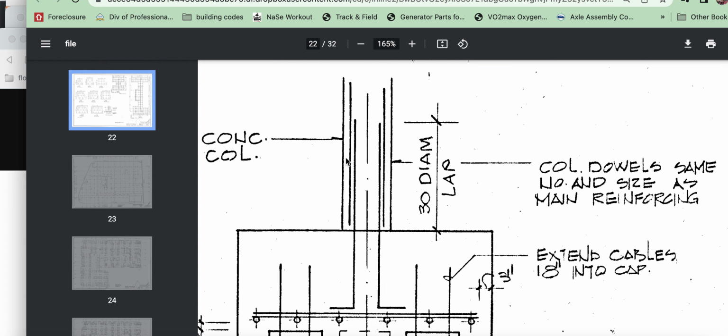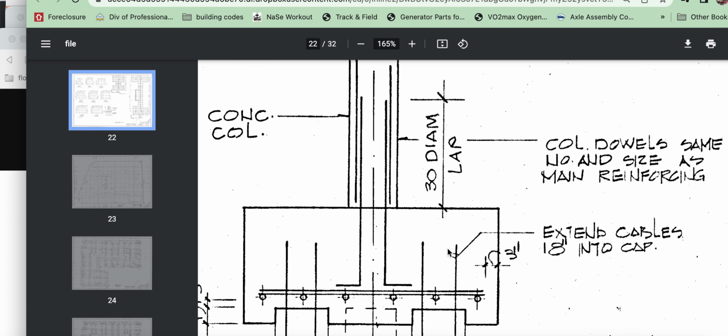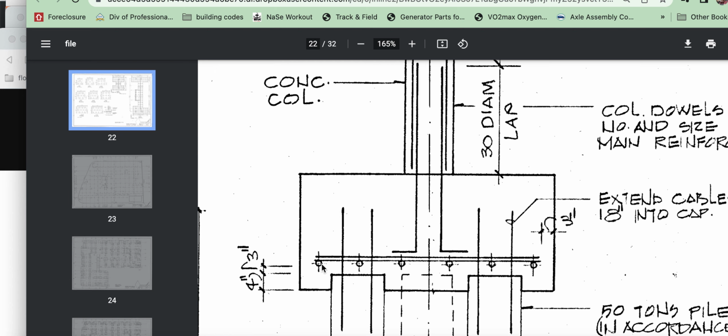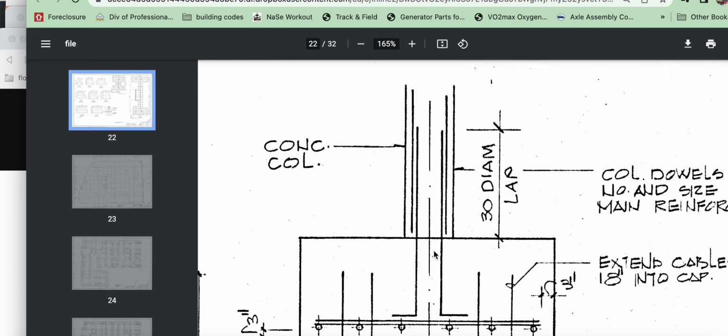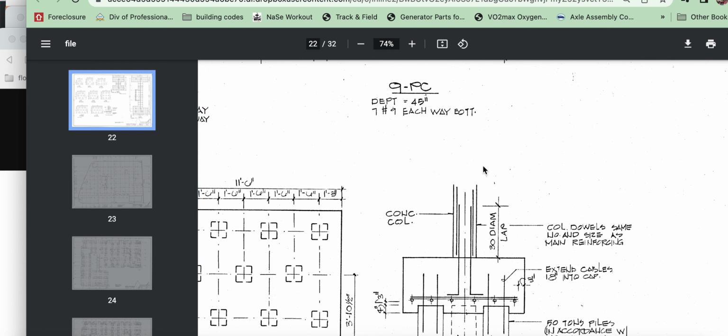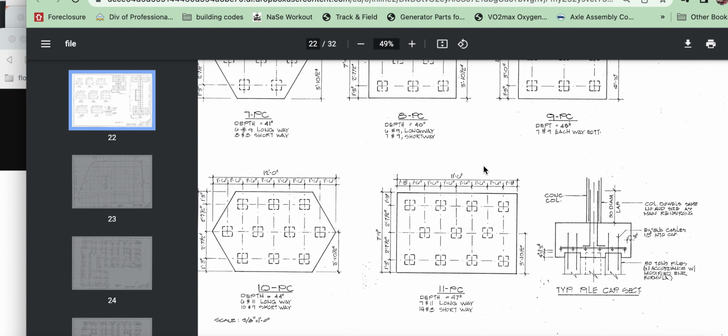And this is the outside of the concrete. So rebars here. They usually indicate it with this little circle tag like that. And this is where they want this rebar, which would be 3 inches up, 7 inches off the bottom. And it would tie across all 3 of these columns. So it would look kind of like a triangle, mostly. And we'll go to the left.